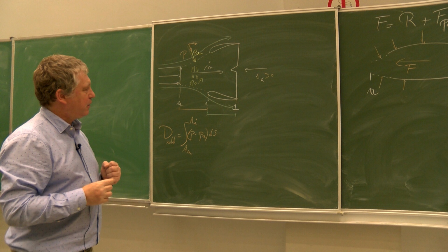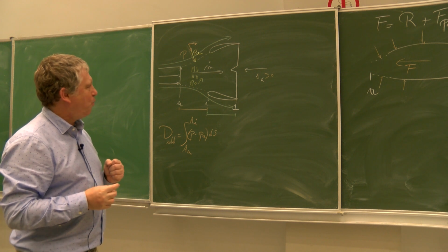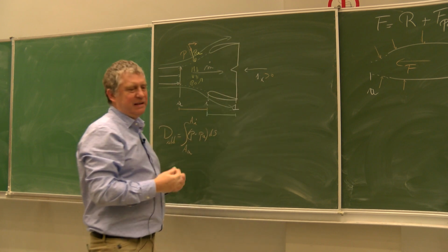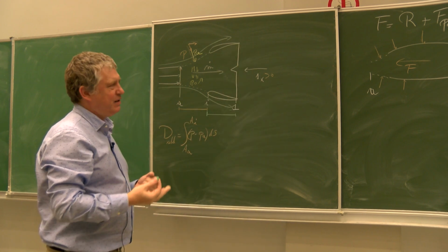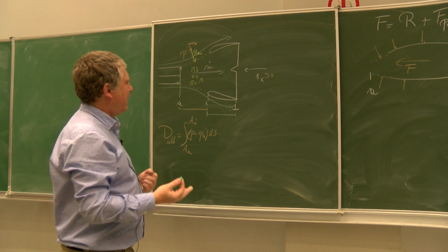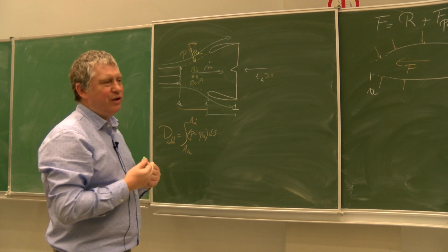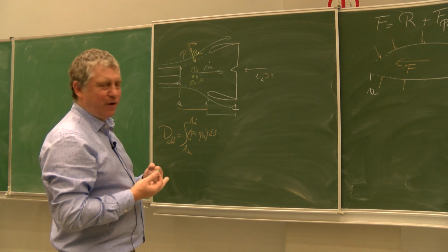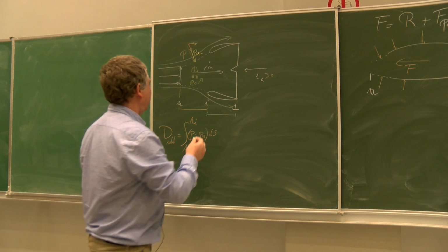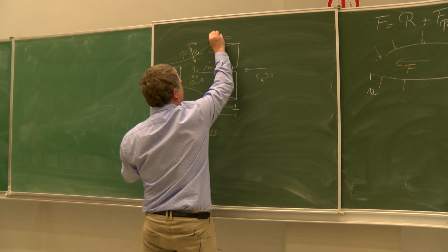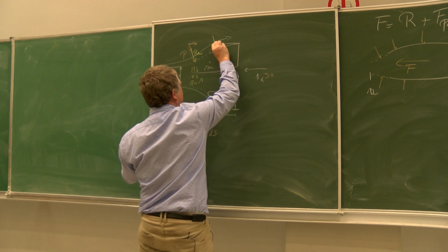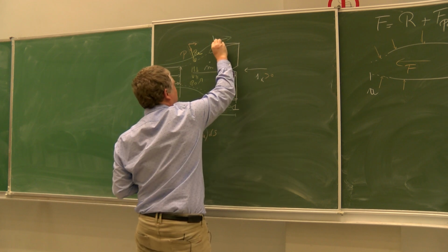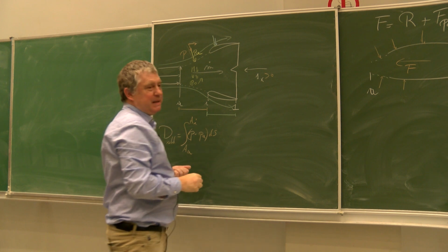For the part between I and 1, we have a flow that is, in fact, like on the suction side, on the extrados of a wing. And so there we have an acceleration of the flow, and a decrease of the static pressure. If you compare to PA, let's consider that you have PA here. In fact, the pressure that you will have there will be lower than PA.